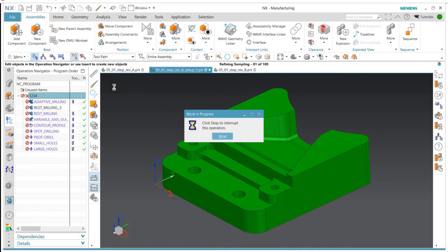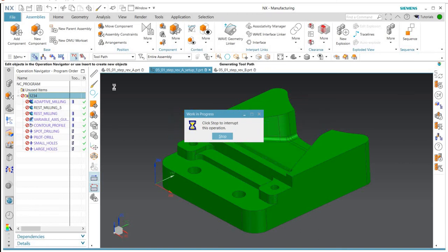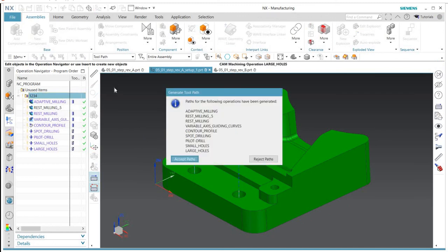If the engineer added an additional hole or a pocket or pad, naturally it's not going to pick them up automatically for machining; you'd have to go in and add them to the operation or create a separate operation for them. Okay, this is ticking along pretty nicely.